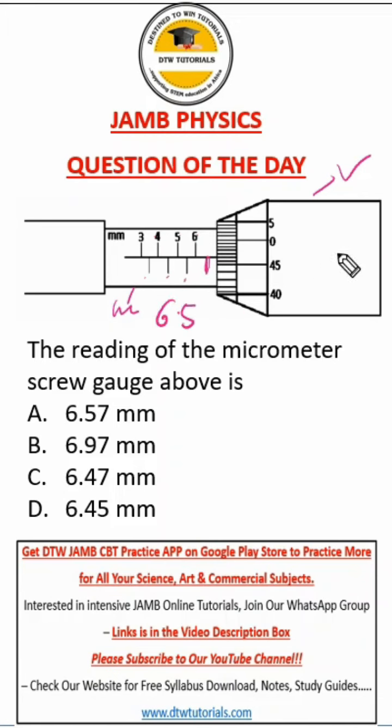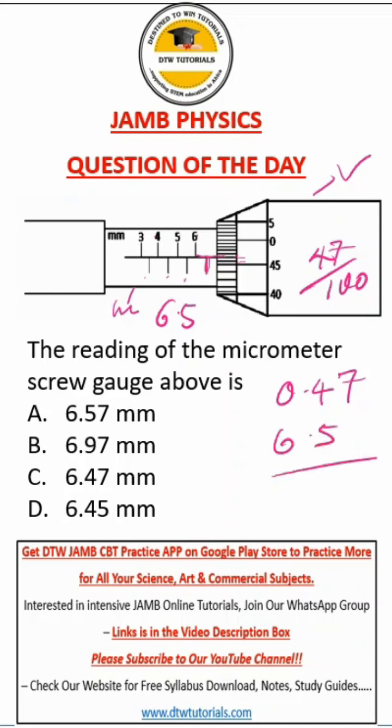Now let's go to the vernier scale. Where this line touches the value on the vernier scale, that would be the value of our vernier scale. So from here, this is 45. The next line is 46. Now 47. You can see 47 touches here. So you have to divide this by 100. Always divide by 100. You're going to get 0.47. Then you add this to your 6.5 and we get 6.97. Our right option here is option B.